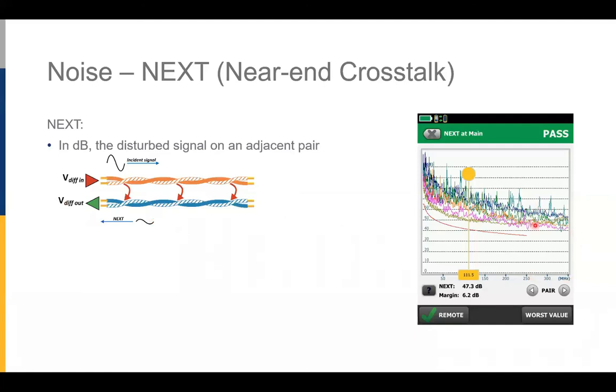Now, on the tester, what this looks like: the vertical scale is the signal in decibels, which compares what we sent out to what we got back, and on the horizontal scale, the frequency. Again, that red limit line is the minimum height of the overpass, and up above we have 6 different pair combinations making these jagged lines. The important thing we can see is that they are all above the limit line, so we don't have an overpass on our highway that's too short.